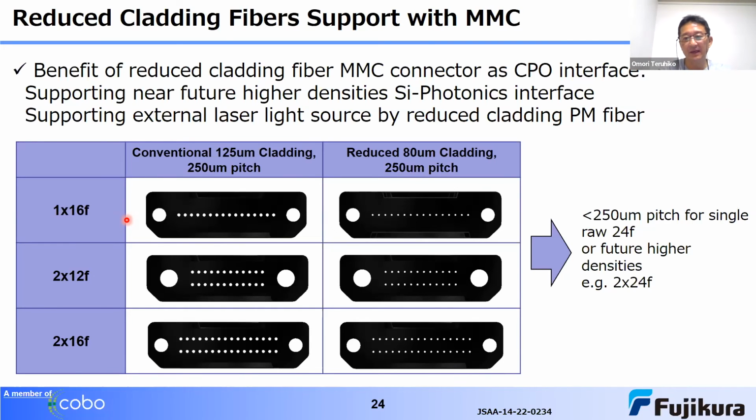And finally, if we employ the 80 micron fiber with 165 micron pitch, we can design a single row 24 fiber in the future. It means that in the future, a 2x24 fiber connector will be available.